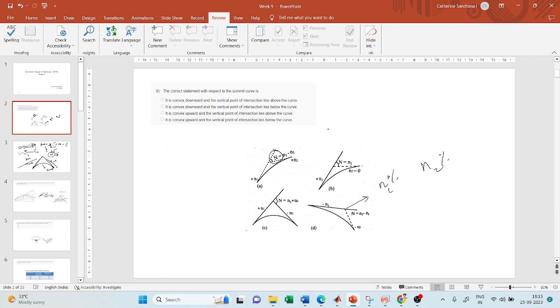I should take two grades and subtract them, that is called the difference. When the term algebraic comes in, it means that I should take the sign of the gradient into consideration. It doesn't mean that I should just take the numerical values and find the difference, but I should consider the gradient as it is, including the sign. Say if you see this, what is the algebraic difference?